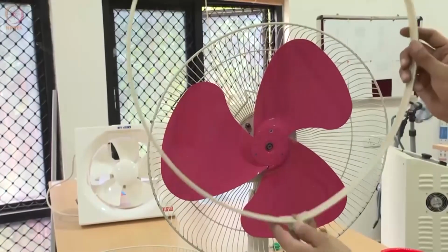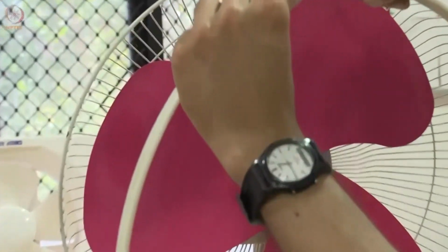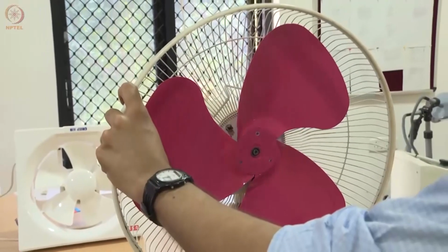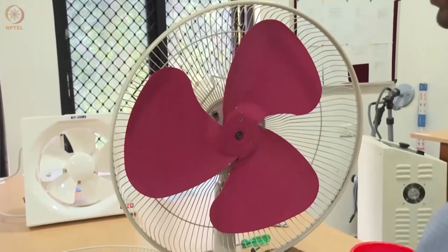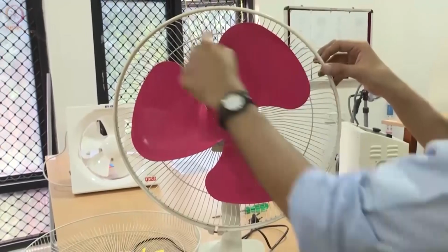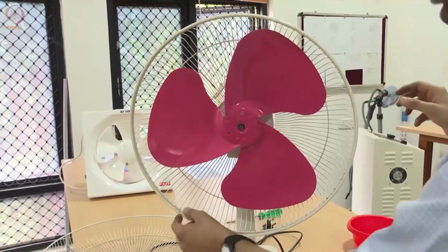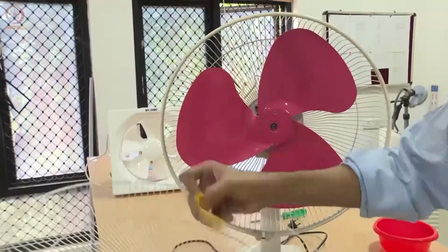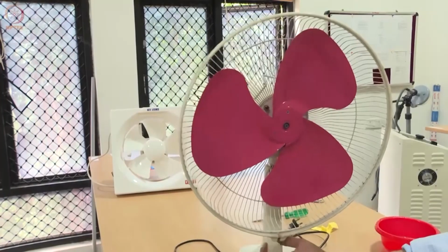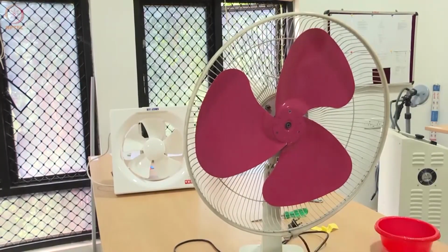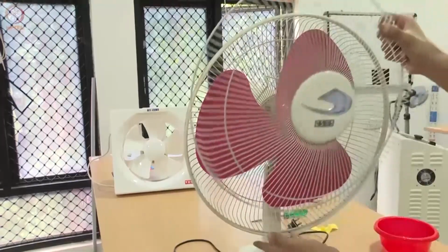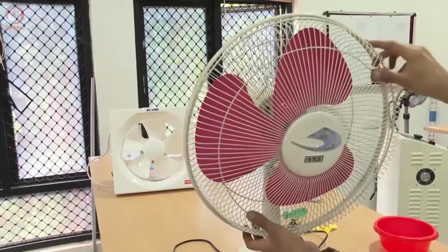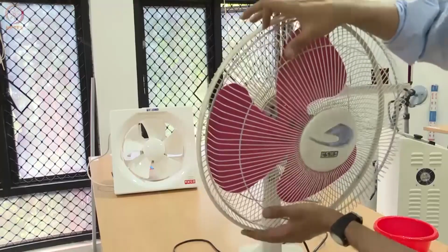So this is important. You don't have to loosen the screw all the way. Just loosen it far enough such that you are just able to slip this ring on the outer, such that the groove properly engages the back grill. Once you do that, make sure the screw is at the bottom so it doesn't interfere with the user. Make sure the logo is aligned to the front. I'm resting the bottom part of the grill on the groove, so I can slip it past.